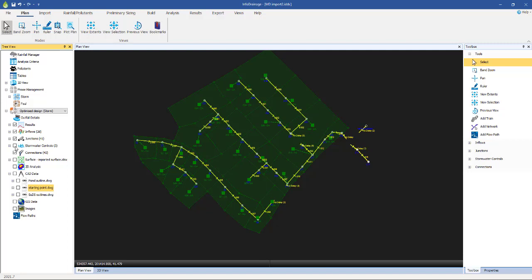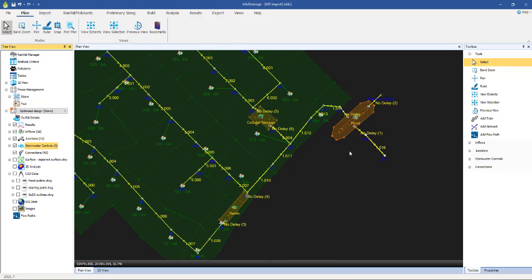And then what we've got is the stormwater controls. So these could be the ponds, the swales, the bioretentions, the permeable car parks, those sorts of storage structures. That's the 4th building block. And finally, number 5 is the associated inlets and outlets. So we're talking here about things like hydro brakes, orifices, pumps, weirs, any of those sort of aspects. So those are the 5 main building blocks.